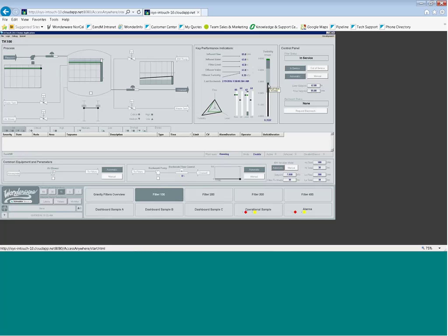So I can see, again, I'm starting to get a little bit of a low turbidity here. So it just provides that more context for an operator to not have to know from memory or training how does my current value relate to my set point, and how far off set point is a bad situation. So I can just see that, hey, turbidity is starting to get into an abnormal situation.